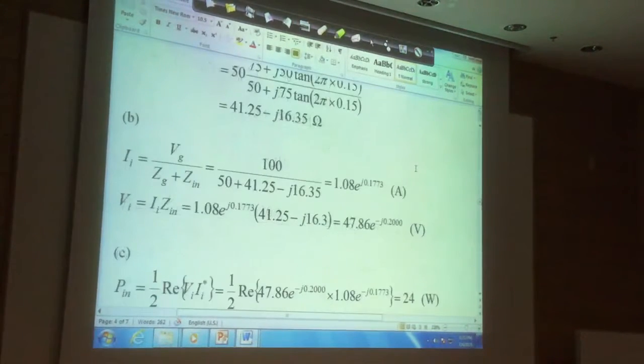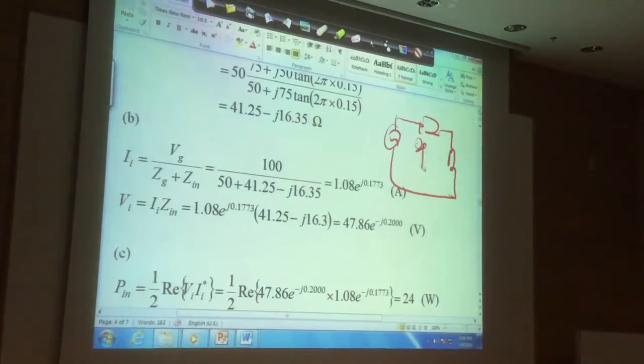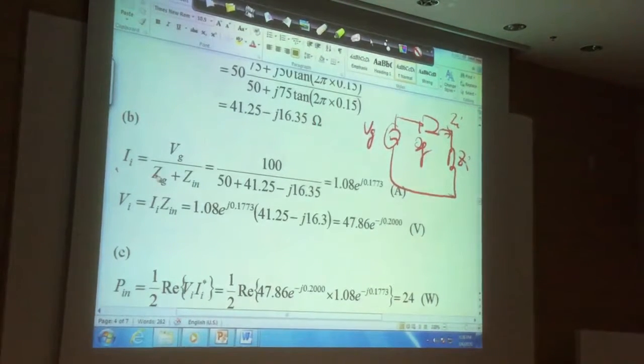Then this also you can verify. Just now mentioned, this has been simplified. This, right? This the VG, the ZI, the VG, right? Then I. This is I. This is very simple relationship, right? This voltage is I times ZI. Okay. So the challenge is to do this complex number calculation.